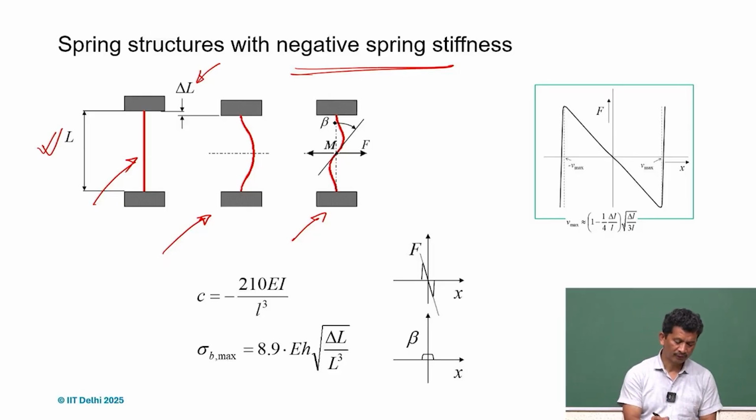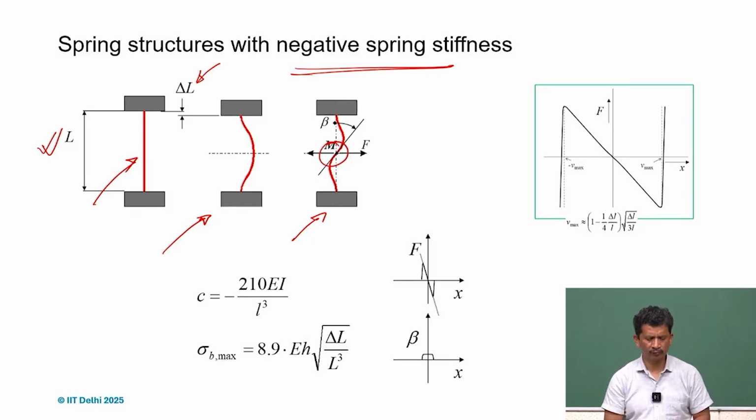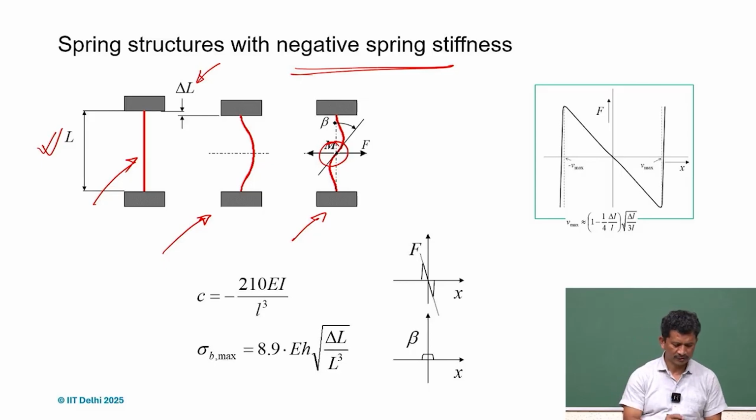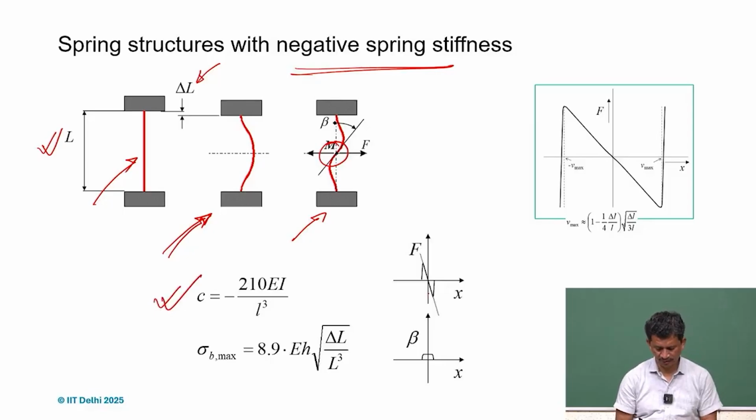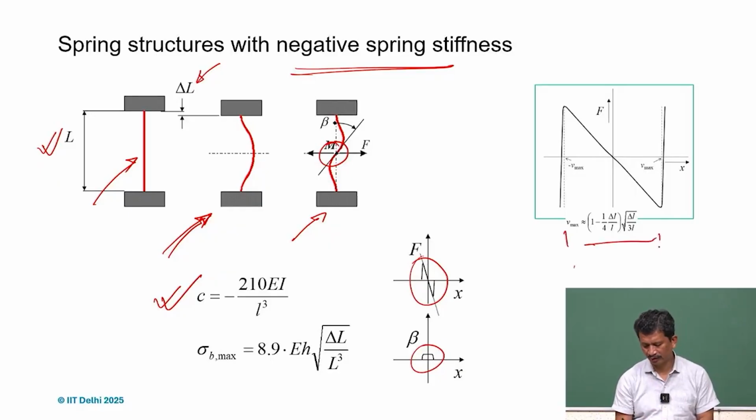And if we control, we can get higher modes, and accordingly we can get different stiffness values. So for instance in this case, this is the stiffness, and you can see the range of motion is very small, so it works only for a small range, and it's magnified now. So that is the displacement range we are talking about, and in that range we'll get a negative stiffness because we have to always apply force negative to the displacement required.